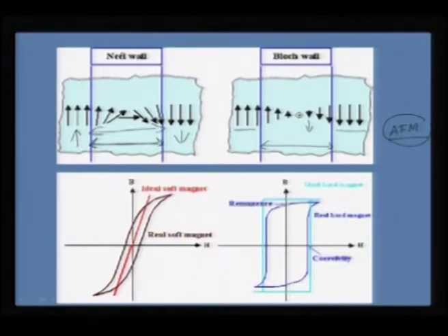Depending on that, you can look for different shapes of hysteresis, and this is one such shape, which is a typical hard magnet, where you will almost get a rectangular hysteresis loop. This is seen for hard magnets where you have a very large coercivity and very high remanence, because this is your saturation, and the saturation and remanence ratio, Ms by Mr, will be almost close to 1.